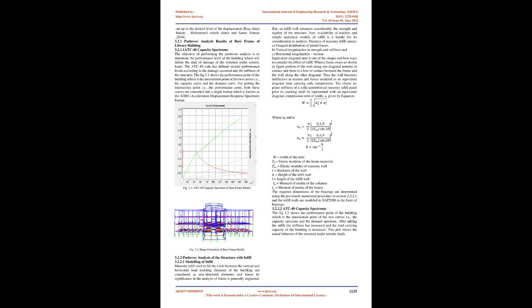Fig 2.4 Roof level. 2.2 Modeling and analysis of building. A ground with 3-storied, G+3, existing reinforced concrete building located in Zone V of India was taken for the investigation. This existing building is designed and constructed using IS 456-1978 only for the gravity loads, i.e., without considering the previous seismic code IS 1893-1984. First, the equivalent static analysis of the building was done under gravity loads and seismic loads. Then compare the critical forces and moments of beams and columns at the face of joint.